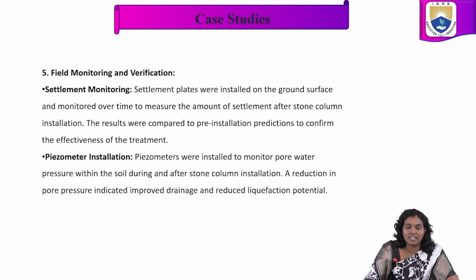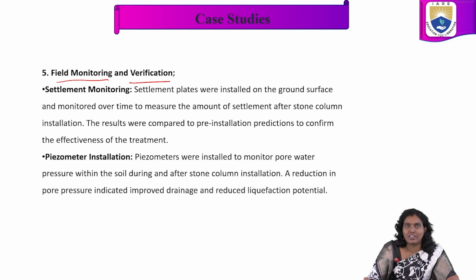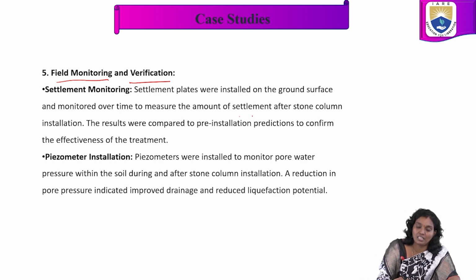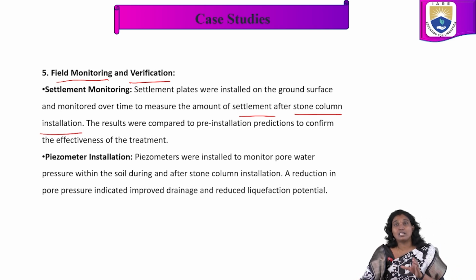Now, field monitoring and verification. Settlement monitoring. In this, settlement plates were installed onto the ground surface and monitored over time to measure the amount of settlement after stone column installation. Whether the settlement is within desired acceptable limits or not, the continuous monitoring helps us understand the soil conditions and also the safety of the construction work.